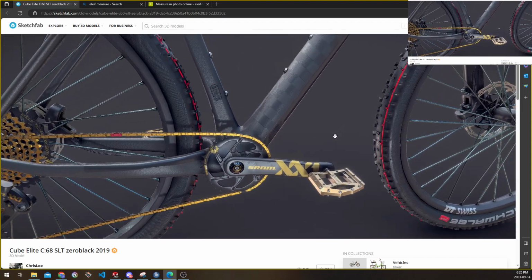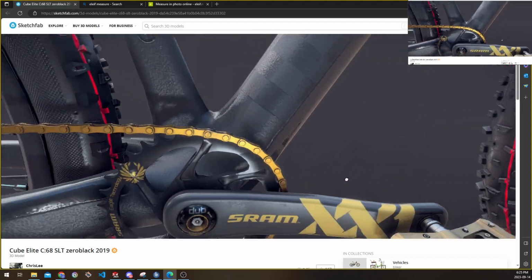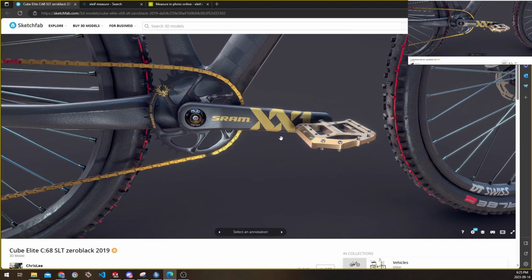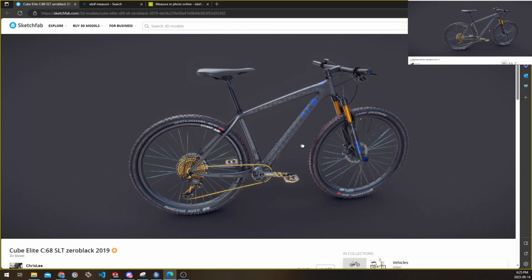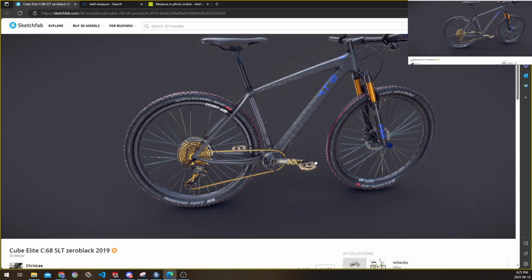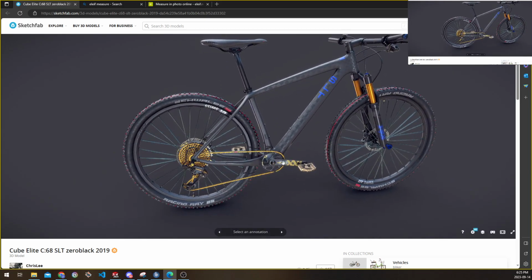No worries. Also, typically we wouldn't want to do this in one part. The reason being, this pedal, right? We're going to be animating this as well. We're animating the motion of this. And that's impossible to do if this is one part, because what will happen is this pedal will rotate with the shaft. And so basically this won't stay flat.